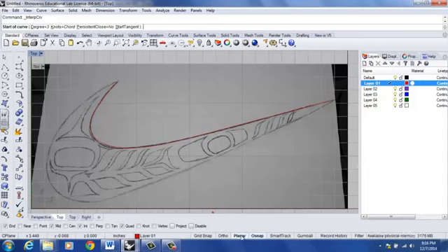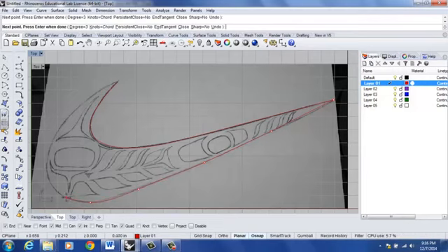The other thing that's really important to note is I want it to be planar, so planar is turned on as well, so that all the curves that I draw here, notice the end object snap as I move over here, snaps, left click. So every curve that I draw here is on the same exact plane. So I'm going to go ahead and left click around. And you're going to notice with the interpolate points, it's creating the curve through the points that I'm drawing, which is really nice, and it's exactly why I use this option. Notice the endpoint followed by enter.